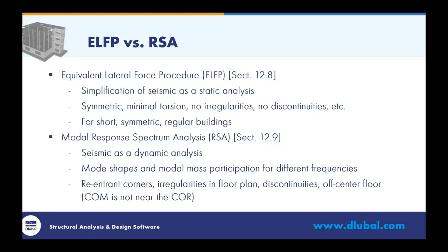And all too often we find ourselves outside of this range. And instead of running this simplified method, this is where we would turn to a modal response spectrum analysis. And this is covered in section 12.9 of the standard. So this takes into account seismic considerations as a true dynamic analysis. We run our modal analysis to determine the mode shapes and modal mass participations for different frequencies of our structure.